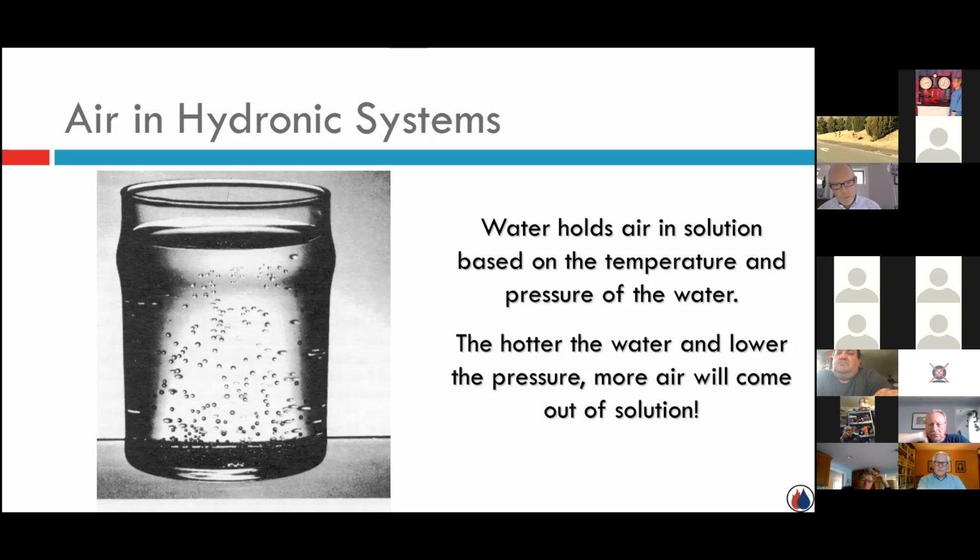What they're trying to show here with this quick example of a glass of water is, you could do your own little example. You went over to the tap, took a glass, filled it with water, put it on the counter, walked away, and came back X number of minutes later, you'd start to see these air bubbles gathering along the sides of the glass. Where are they coming from? They're coming from the fact that we lowered the pressure and the water's starting to warm up to only room temperature. Imagine it being 180, 190 degree water, a tremendous amount of air comes out of solution.